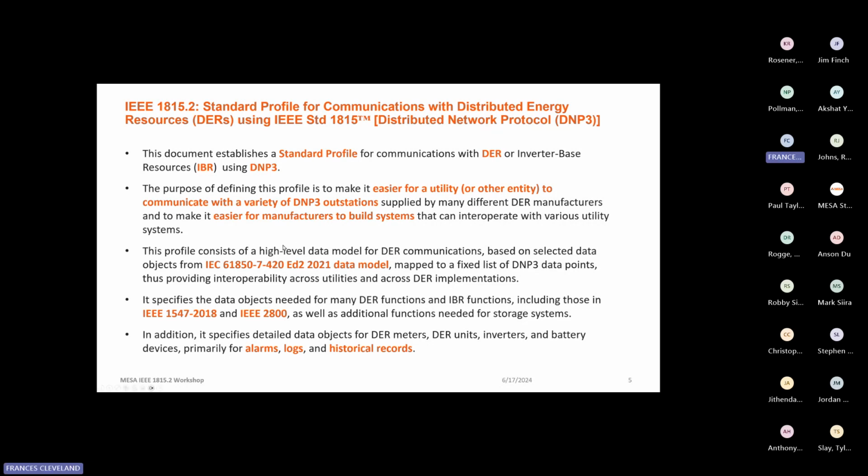The profile consists of a high-level data model for DER communications based on selected data objects from IEC 61850-7-420, the 2021 data model. And the names from these 61850 data objects are mapped to a fixed list of DNP3 data points for interoperability.